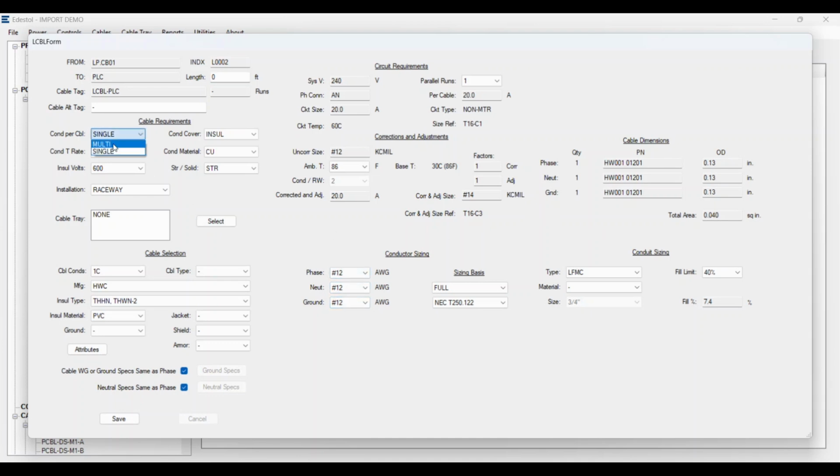This can be in the field, so let's just run a 3 conductor. We may down the road run through cable tray. Let's pick non-metallic, 3 conductor, and then we want to go with the tray cable exposed routing, same rating as our power cables, and it's still 600 volt insulation. So we could put this L cable in the same control power cable tray as our P cables because they're all 600 volt insulation. So there you go, we've selected that. We're down to 3 conductor number 12.